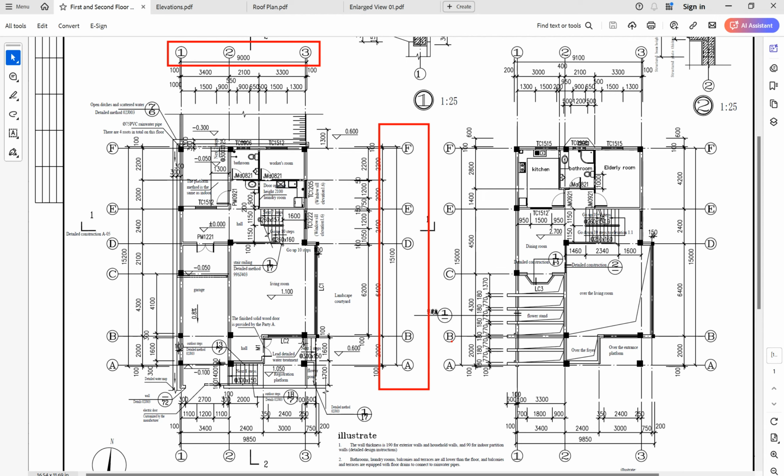But I always teach how to create levels first, and then how to create the layout grid lines. The first thing you need to understand and do is level. Level is more complicated. As a professional, before you put grid lines, you put the levels first.